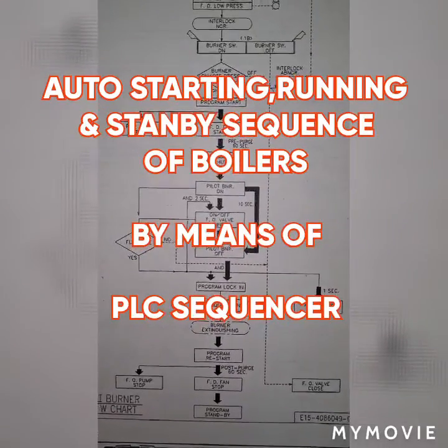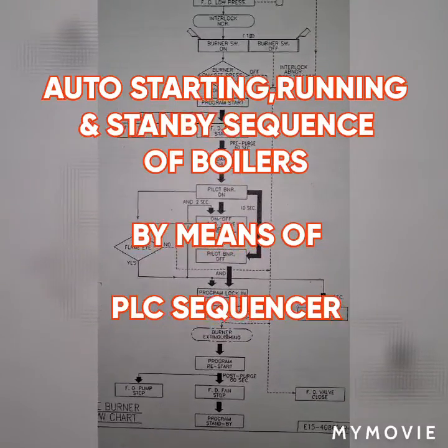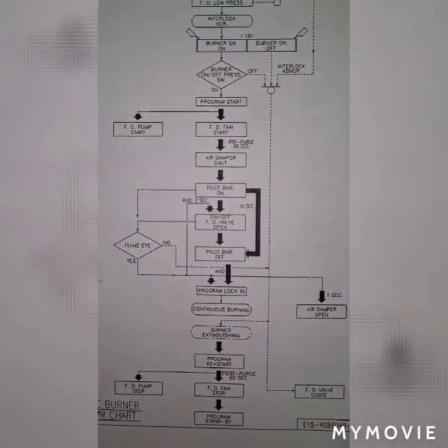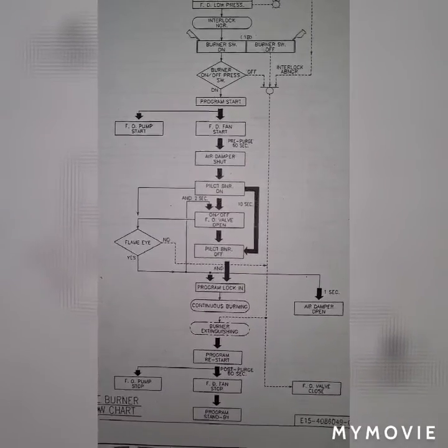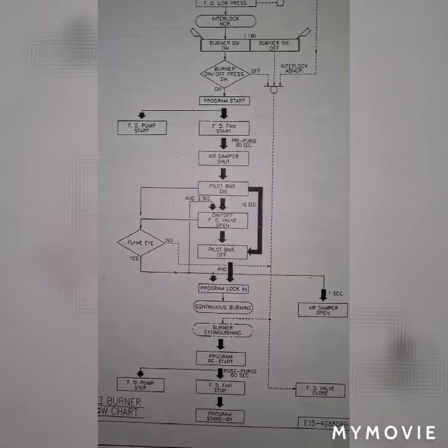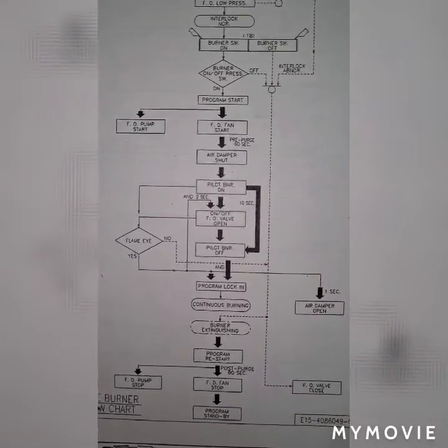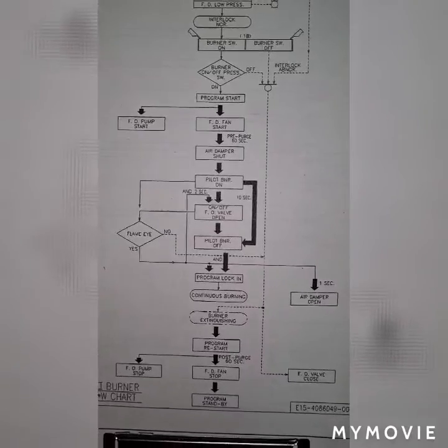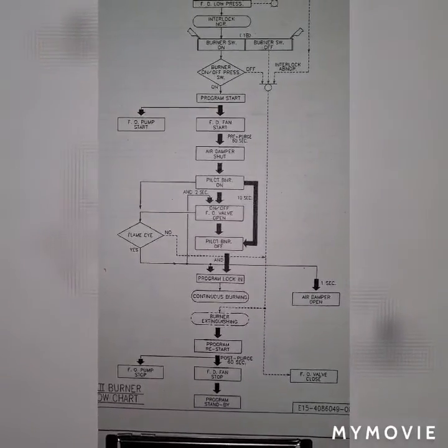Okay, since my boiler is designed to have a maximum steam pressure of about 0.59 megapascal, it will start again when the pressure is between 0.47 to 0.49 megapascal.